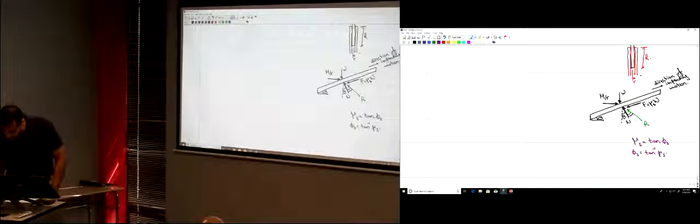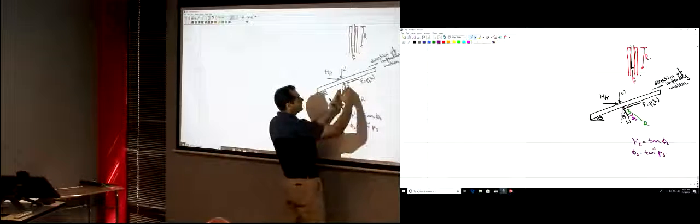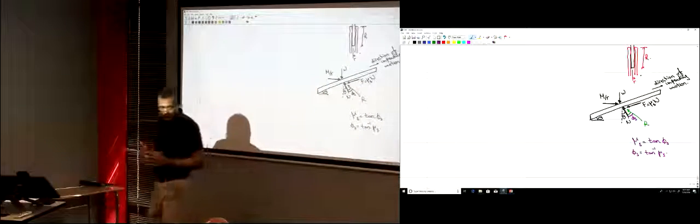So now this angle is phi s. So now we have this resultant force R, which was the resultant of those two forces. Now I would like to resolve it into two components in the y and x direction. Why am I interested in resolving it into two components in the x and y direction? So that I can apply my equations of equilibrium in the x and the y direction. So that's what I'm going to do here. I'm just going to resolve this R into two components.